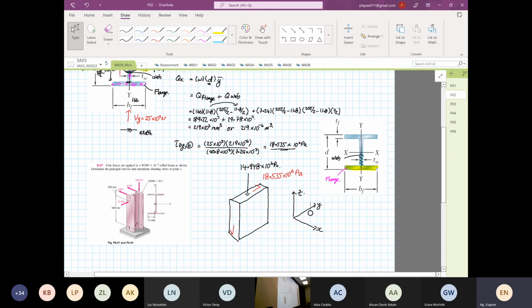Because in the civil engineering world, how do you know the mechanical properties of soil? All our structures are resting on soil, yes or no? So when they are unsure, when the weather is so bad, when it rains, the soil soaks up the water, and the mechanical property changes. So for civil engineers that build structures, it is okay to use a safety factor of 8. For them, it's fine. For us, no go. We design things that move. If we're going to design a building, go for it, follow what they are doing. But we can't do that.